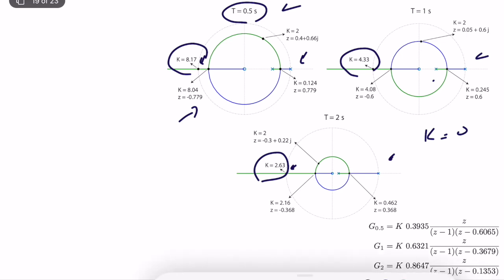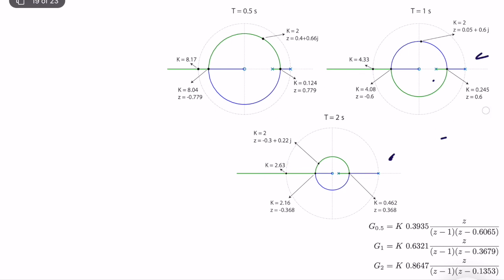So we have a better range here, and I can pick larger gains, which is good because in general, larger gains improve your steady state performance, and having a better range is always good. The second step is, what if I keep my K constant, for example, 2? For the same gain, how can we compare performances? I will show you some results. So K is equal to 2. We are here.